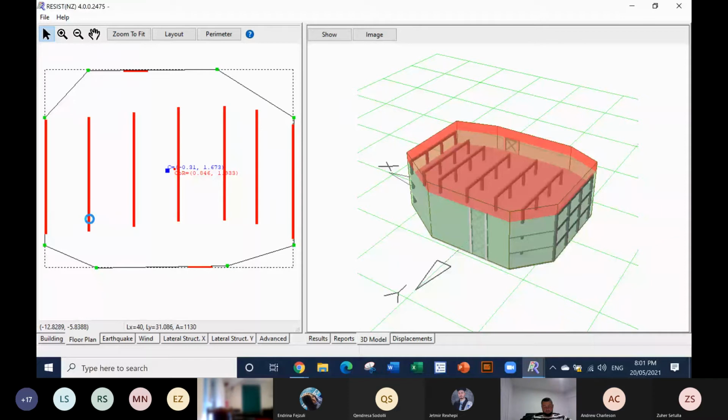Say now I'm integrating the gravity resistance with the earthquake resistance in the Y direction. And so now these moment frames I've provided will also support the floor slabs. Now I've got 2, 4, 6, 7 frames. So if I go to the Y direction, I've got 7 frames.